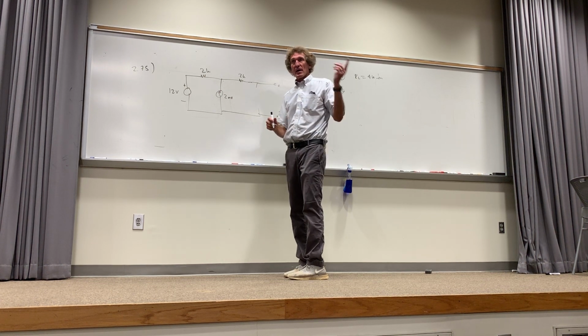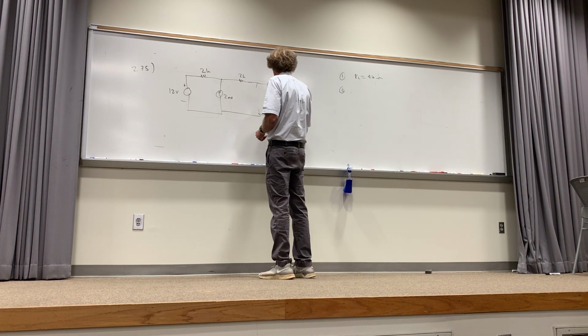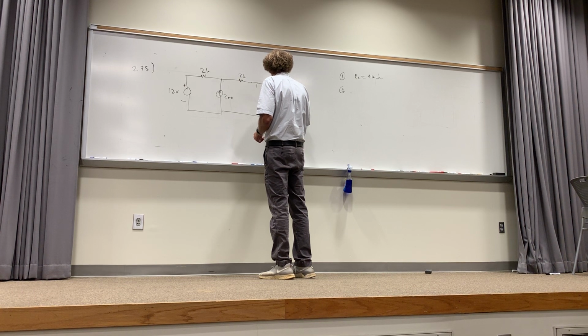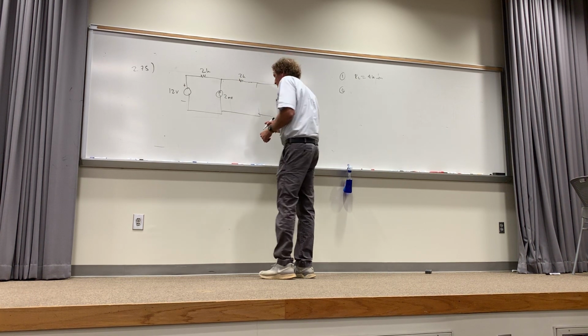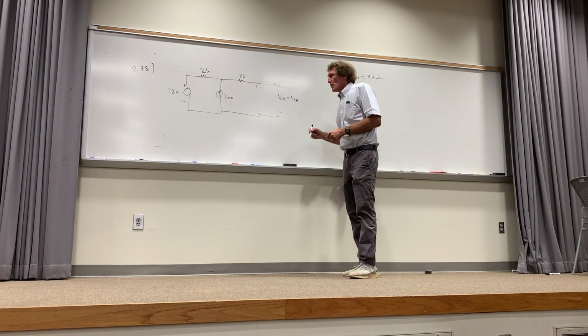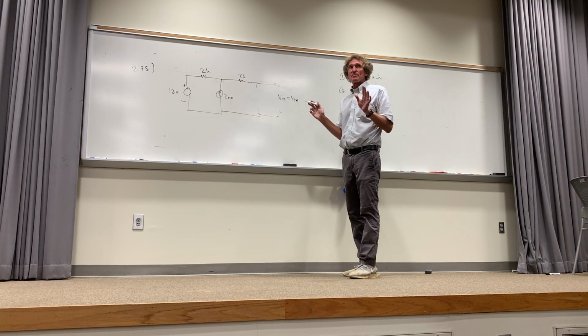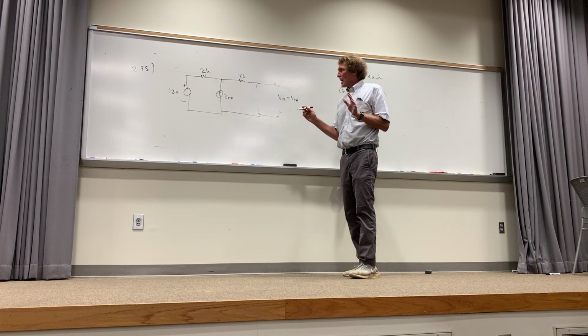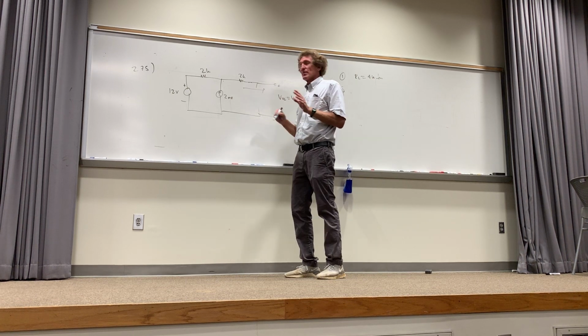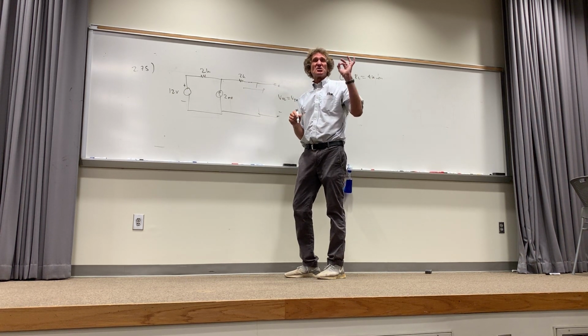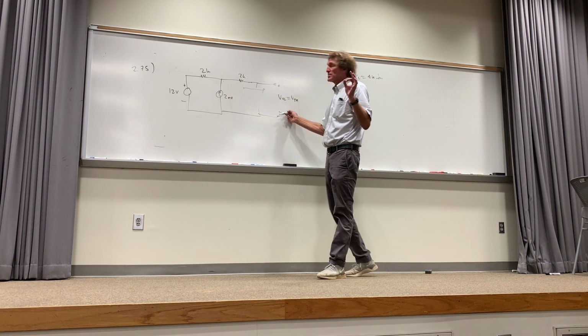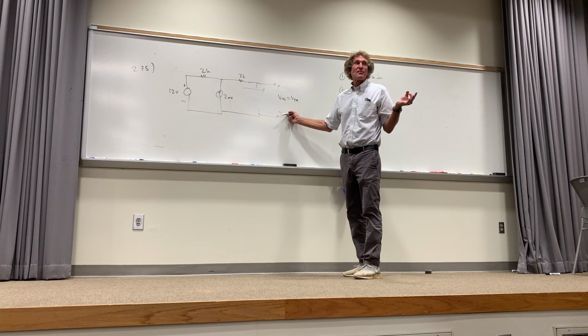Now I want to find my voltage right here, right? Please watch this. So I want to find V open circuit or V Thevenin. Now to do that, what do you see happen? I want you to just see how simple this becomes. How much current can flow this way? Just tell me. 0, right? Why not? Because it's an open circuit. Nothing can flow around there.